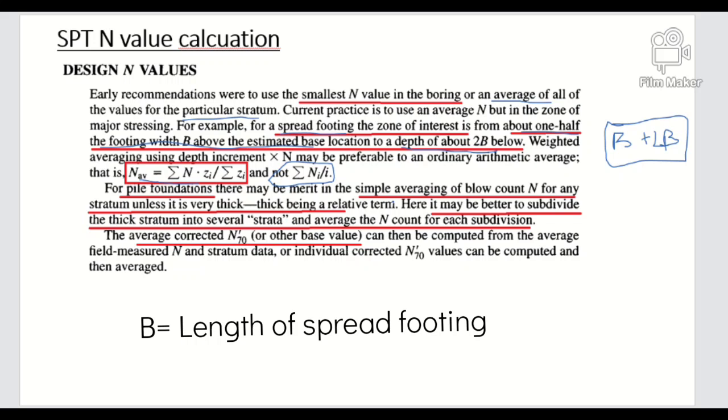If it is a pile foundation, the blow count for any strata is a simple average. It will not take the arithmetic average. For spread footing, it takes the arithmetic average, and for pile foundation, it takes the simple average. This is to be noted and remembered when we design any foundation.